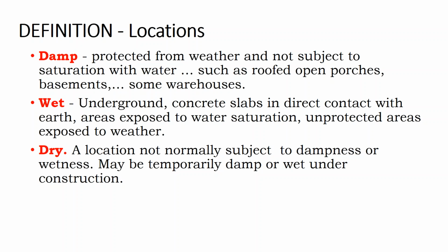PV cable in general, when it's cross-listed to go inside of conduit, and it usually is, you get caught up because it has that thicker jacket. If you're just using generic rule of thumb guesses on how many number 10 cables can fit into a conduit, you might surprise yourself if you're using PV cable. You take an equivalent gauge solar cable and you wouldn't be able to fit the same number of conductors as utility service entrance conductors with thinner jackets into the same sized conduit.